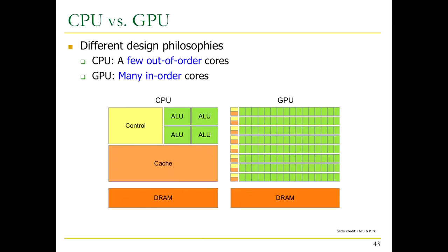On the GPU, we essentially have a lot of small cores that we are going to call stream processors or CUDA cores. Whenever you see each of these green squares, this is each of the vector lanes, each of the vector functional units that we have inside one shader core. We will see a better picture later.